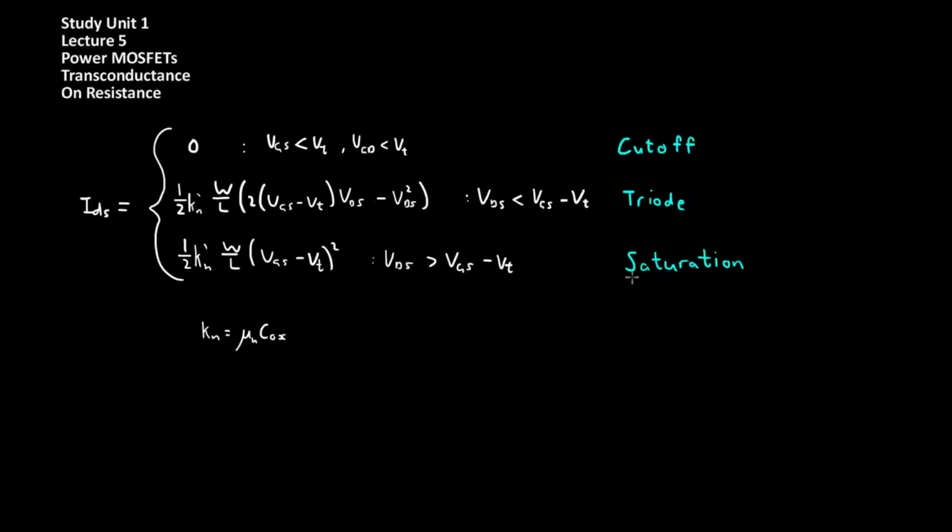When the transistor is operating in saturation, this is considered from a power electronic standpoint as the fully on state. In this state, the transistor is normally considered purely resistive, with the on resistance as a sum of the epitaxial region resistance of the silicon, the channel resistance, which is the resistance of the channel under the gate, and which is modulated by the gate source voltage, and finally the lead and connection resistance. It is for these reasons that MOS transistors are designed to minimize the RDS on of the transistor to minimize the voltage drop when conducting current.